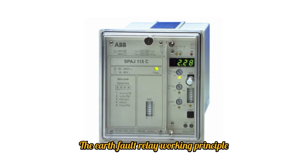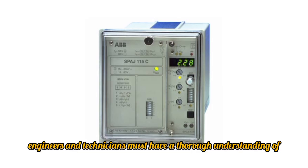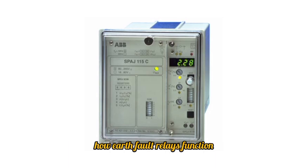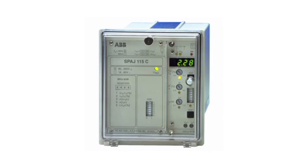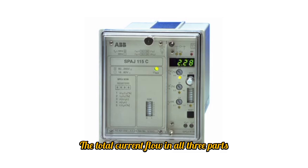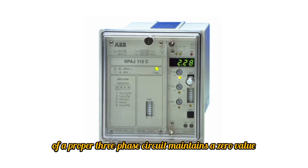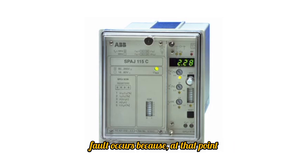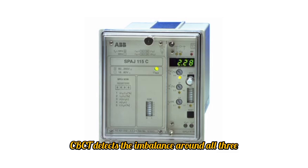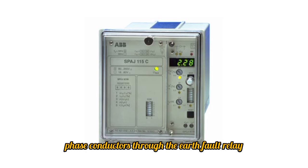Earth fault relay working principle: engineers and technicians must have a thorough understanding of how earth fault relays function. The functioning principle of these relays depends on detecting residual current flow. The total current flow in all three parts of a proper three-phase circuit maintains a zero value. The ground path operates normally until a fault occurs because, at that point, some current passes through it, leading to an asymmetry. A core-balance current transformer called CBCT detects the imbalance around all three-phase conductors through the earth fault relay.